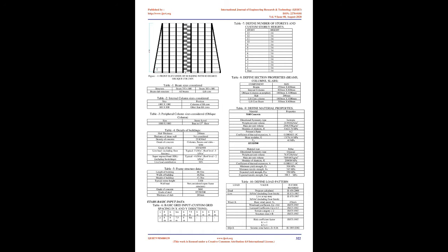3. Methodology. 1. Extensive literature survey by referring to books, technical papers, or research papers carried out to understand the basic concept of the topic. 2. Identification of need of research. 3. Formulation of stages in analytical work which is to be carried out. 4. Data collection. 5. A 13-story building is considered for the analysis. 6. The model is prepared on ETABS and planned on AutoCAD for the several angles of inclination of buildings with oblique columns. 7. Wind loads and earthquake loads for the building according to IS are calculated using the various parameters. 8. Application of calculated wind loads and earthquake loads on the modeled buildings is to be done.